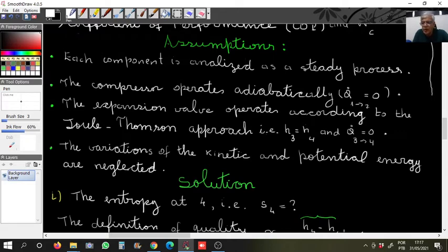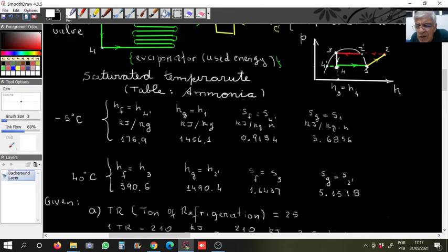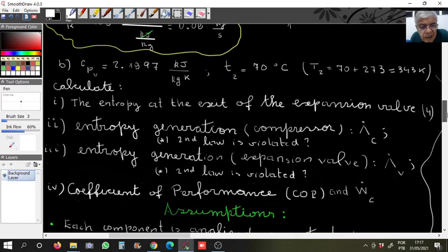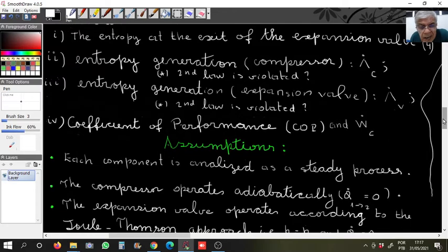Q dot from 1 to 2. Attention now, the compressor is the state, look, from 1 to 2. It's an adiabatic process, but it's not isentropic. Attention now, it is assumed adiabatic. In some exercises, they assume also isentropic. This will be helpful.